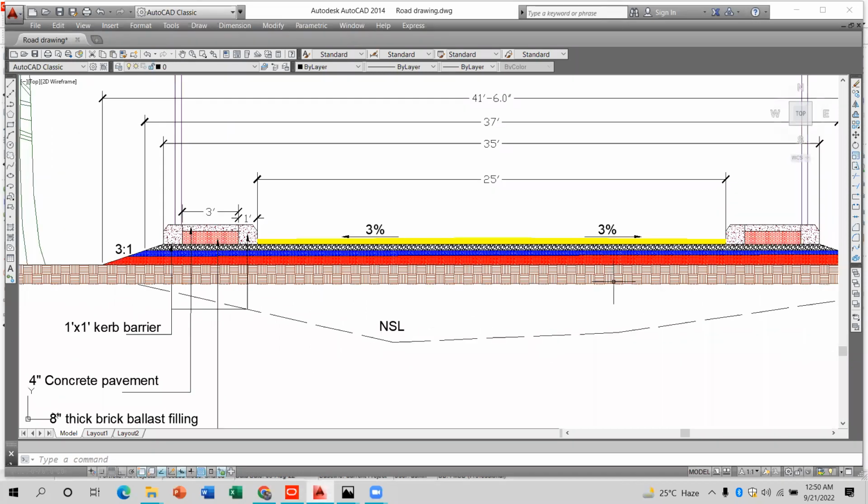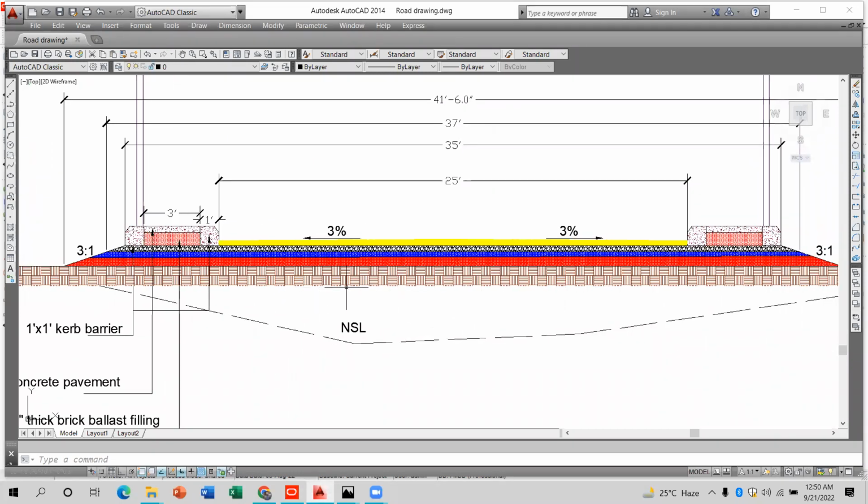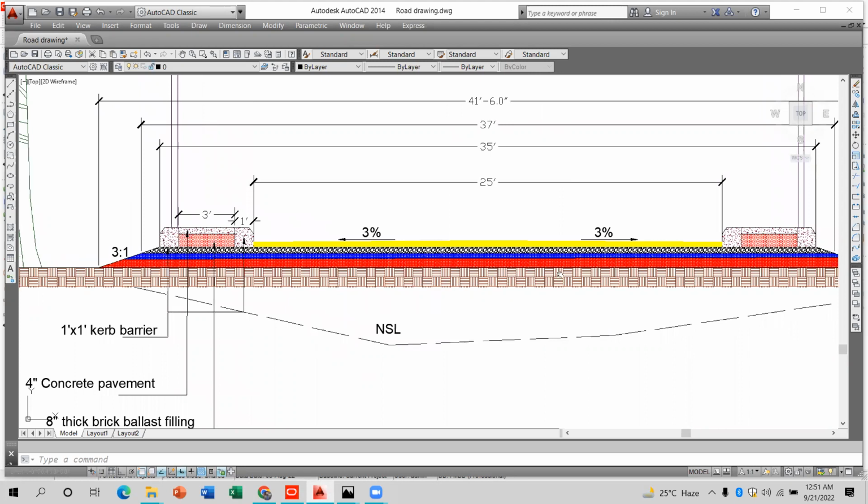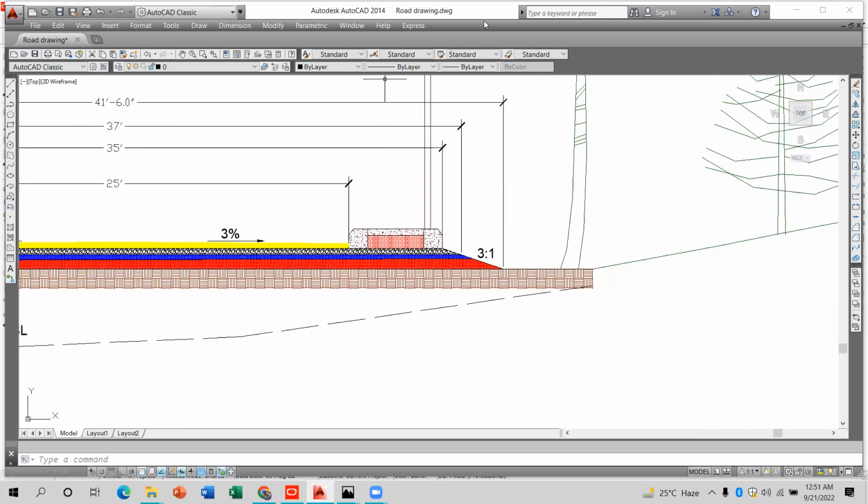Okay, now you are on the level of the subgrade. Now into the subgrade, always remember that there can be two layers of the subgrade, subgrade bottom and subgrade top. There are 2 layers, normally about 15 centi and 15 centi, and 95% compaction is required for it.